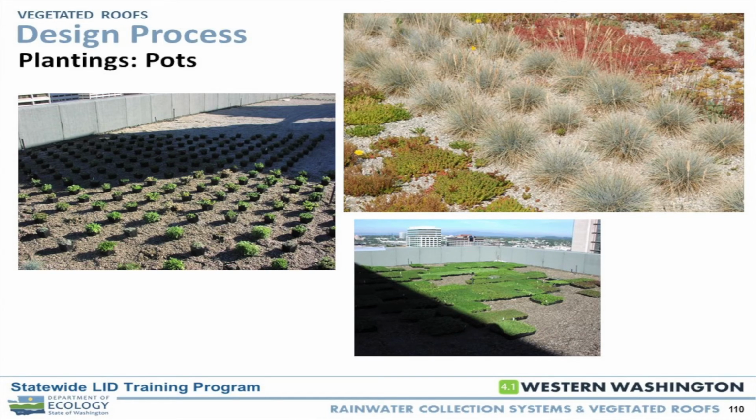The other thing that's happened is we found that every time you bring in these pots, they come in with their own soil that they were grown in. So you're introducing a very different soil than your very engineered media, for one. You're also introducing weed seeds and other potential issues. We've had projects where we brought this in, it looks great, and then weeds start shooting out of every single pot, and then they start colonizing, and you create this really interesting maintenance dilemma. You're doing all this work to keep the roof clean and weed-free, and then every plant you bring in is bringing in weeds.